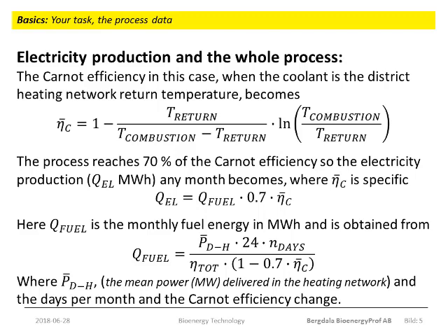Now, to compute the monthly fuel input energy and the electricity production in megawatt hours, you will use the equations shown in this slide. You will notice that the total process efficiency as well as the Carnot limit will change from one month to the next. So you should make use of your skills as a programmer to set up and calculate the monthly data. You will find that the monthly need of input fuel goes from a maximum exceeding 65 gigawatt hours per month in winter and down to some 13 gigawatt hours per month during summer.